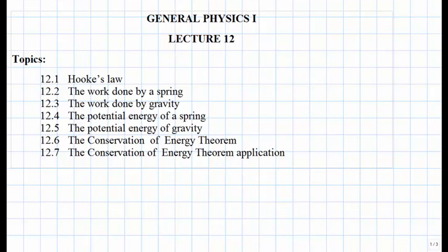Welcome everyone. During this lecture, we'll introduce Hooke's law, the work done by a spring, the work done by gravity, the potential energy of a spring, the potential energy of gravity. We'll also introduce the conservation of energy theorem, and then we'll explore a conservation of energy theorem application. Let's begin by introducing Hooke's law.